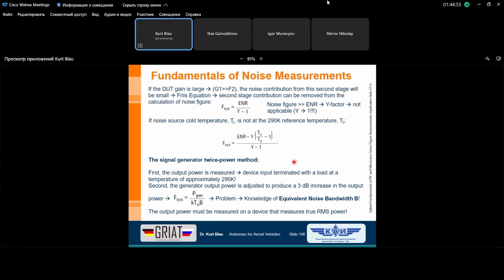Then such power amplifiers deliver, let's say, up to 200 watts at very high frequencies in the X band, for instance between 10 and 12 gigahertz, or at much higher frequencies in the so-called Ka band, in the range of, let's say, 24 up to 27 gigahertz and so on.